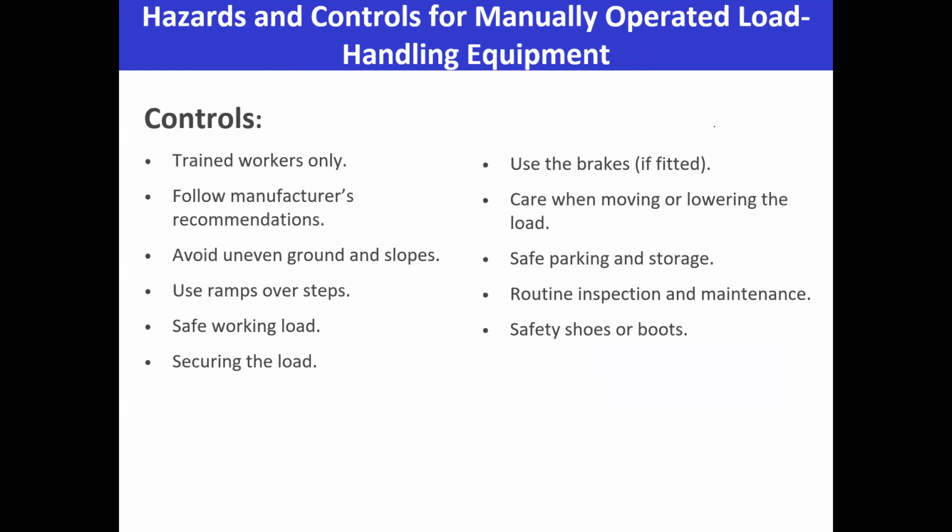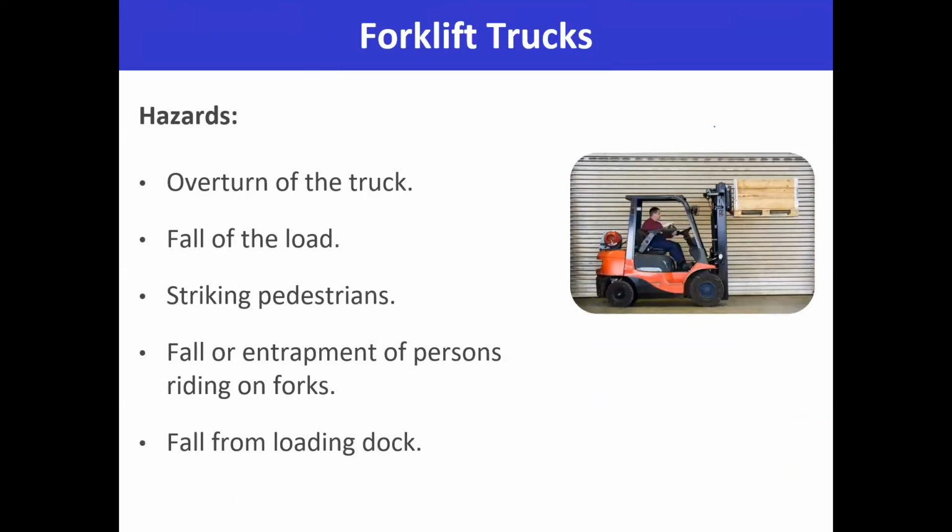What are the controls? You need to use trained workers only, follow the manufacturer's recommendation, avoid uneven grounds, use ramps or steps, observe the safe working load, secure the load, and use the brakes. Make sure the brakes are in working condition. Take care when moving or lowering the load, ensure safe parking and storage, carry out routine inspection, and safety shoes or boots should also be provided.